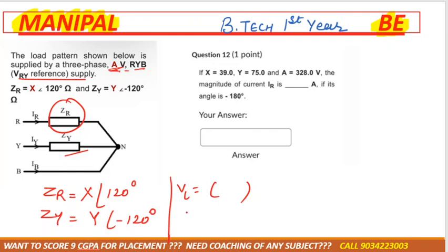So in case of star connection, current is same but voltage is different, right? So if the value of this one, ZR, ZY and voltage is given, we need to calculate the magnitude of IR, and if the angle is minus 180 degree, okay, current angle then minus 180 degree. So we know the formula VPH is equal to IPH multiplied by ZPH, right?